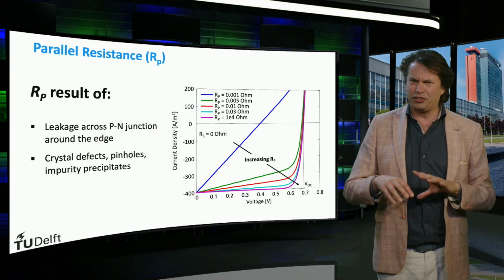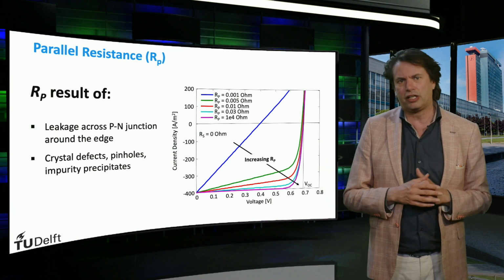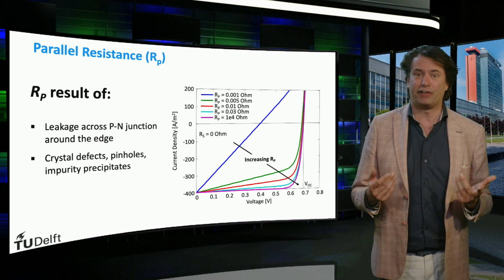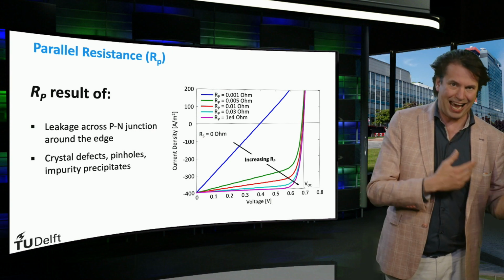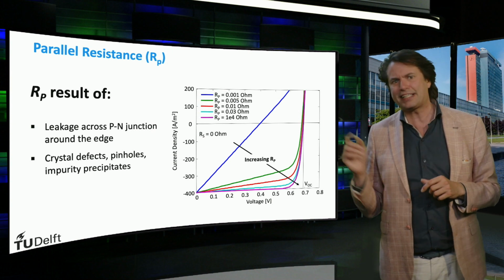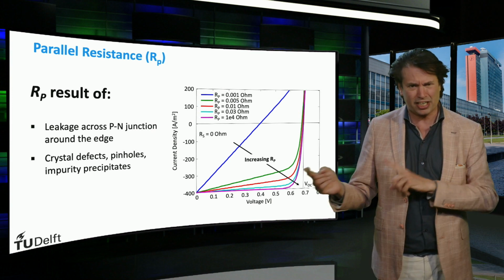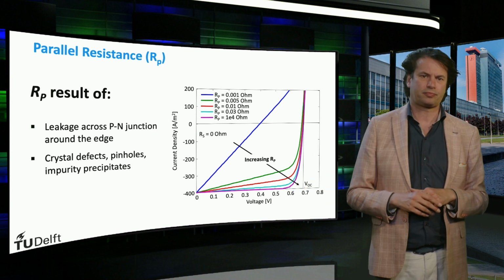The single diode model is good for electrically simulating a solar cell. However, sometimes it is insufficient, in which case an additional dark current diode is added in parallel. In this case, the first diode represents the dark diffusion current, while the second diode represents the dark recombination current.